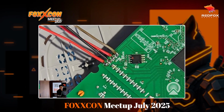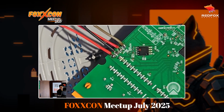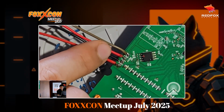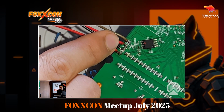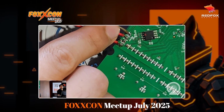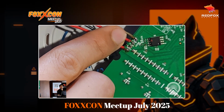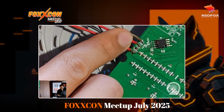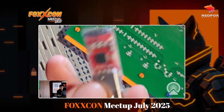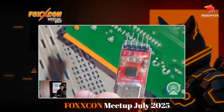So as you can see, not really my best soldering job, but it does the job anyways. So yeah, I've connected these 4 wires. Now the point is, sometimes you will be lucky enough to find these ports being named. As I told you, it needs power, it needs ground, it needs transmit, and it needs receive. So all of those things you might be finding, like we did on this specific device, like it's being named, right? You can see it, right?